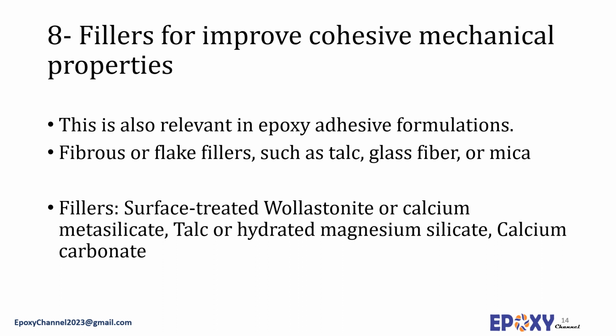Calcium carbonate filler is a particulate filler which can improve the physical properties of epoxy resins such as tensile strength, tear, and elongation. The combination of particle size and surface treatment is critical in the selection of precipitated calcium carbonate fillers to obtain desired properties.